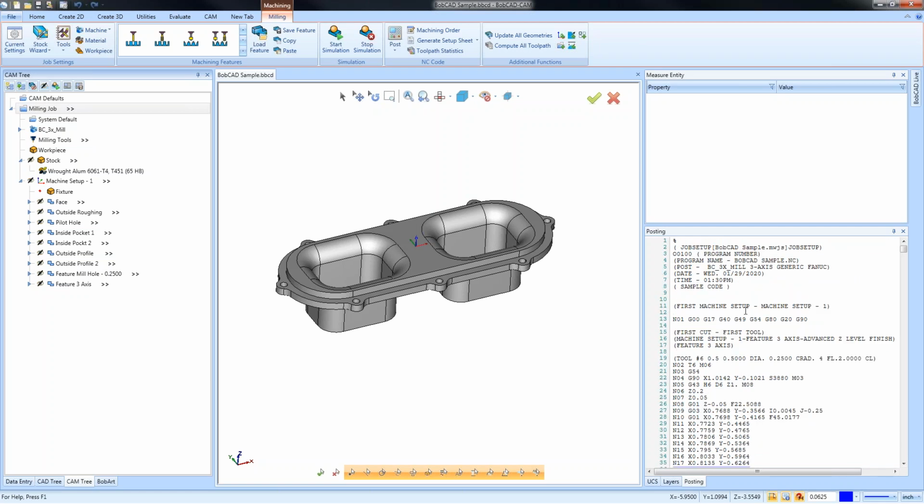stuff dialed in. Op stops at the end of the operation, tool numbers just for tool calls, staging tools, list of tool program, or list of tools at your header. All of those things are possible with the post processor, and really just an average skill set. If you get into some logic and script writing, then you need to go a little bit higher with the post API and advanced posting blocks.